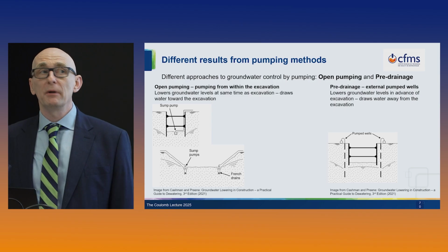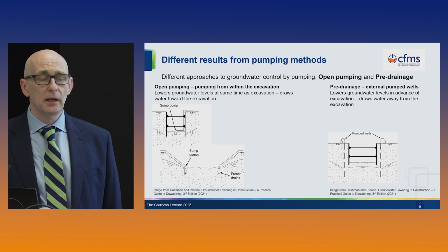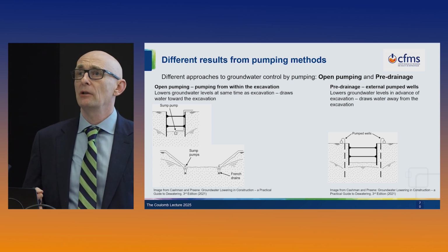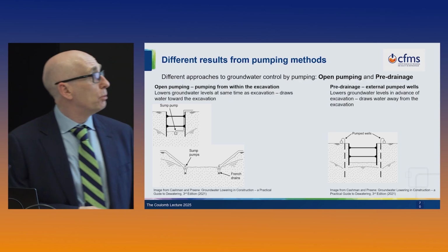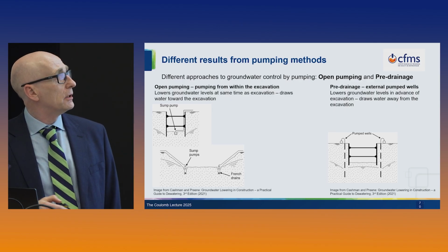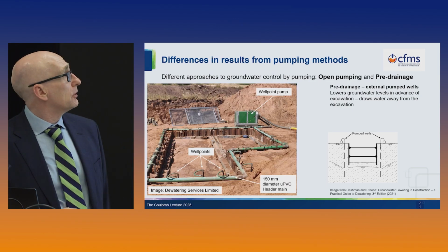The alternative pumping method is pre-drainage, and that is where a series of pumped wells are normally installed on the outside, and it means we can pump on these wells and we can lower the groundwater level in advance of excavation, and broadly speaking we're drawing the groundwater away from the excavation. This is what it looks like in practice.